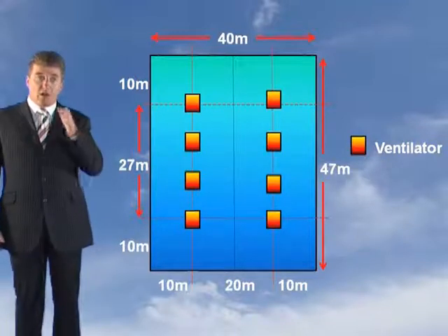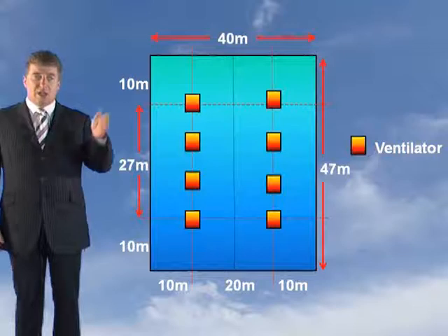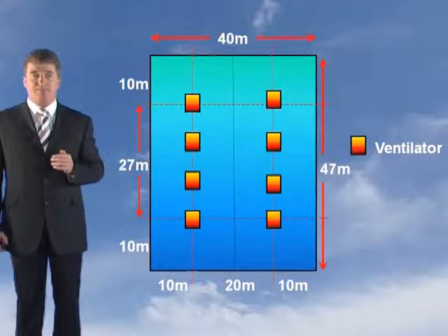Can you see on there? We need at least 8 ventilators located as we have there. And those 8 ventilators must have a minimum area of 43.47, so there must be at least 5.3 square metres each. So that is what they've got to be geometrically. Now that covers step 8. So we know now how many ventilators we need and how big they're going to be.